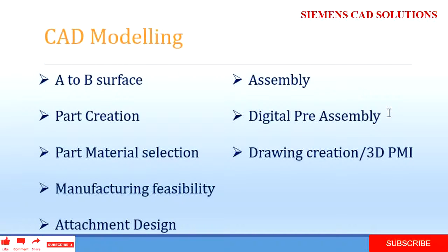So in this process, they will assemble the parts with the environmental data, and they will check the clearance and standards to maintain. For example, for the dynamic parts we need to maintain around 19 mm for metal to metal. For plastic to plastic we need to maintain 12 mm clearance, and for the standard parts we need to maintain 6 mm. If there is any interference condition, for fasteners it should be an interference condition. Those things also need to be checked in the pre-assembly.